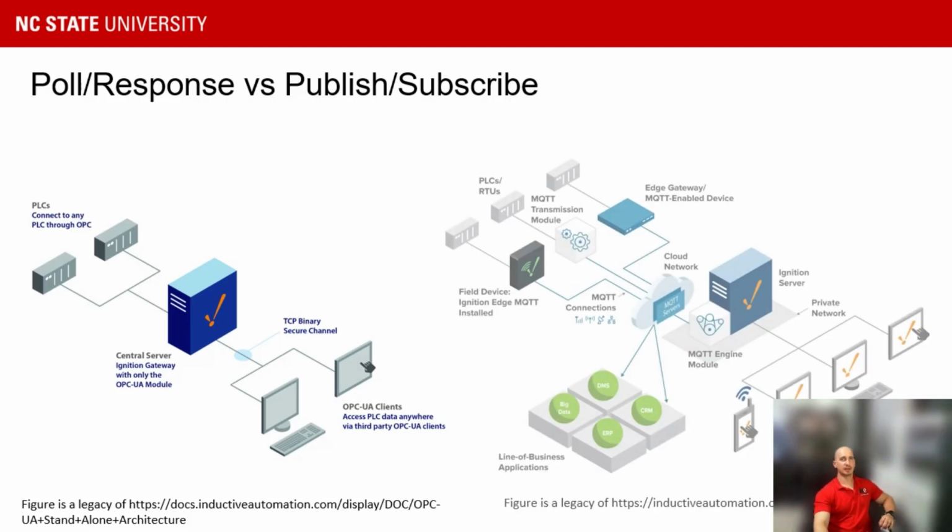On the other hand, a publish-subscribe type messaging architecture can alleviate the concern of the poll response approach by decentralizing data flow. In MQTT, every machine asset can talk to any other machine asset within the factory floor via a broker. Recently, the OPC Foundation released a PubSub model specification to implement the same data structure through other application layer protocols such as AMQP or MQTT.